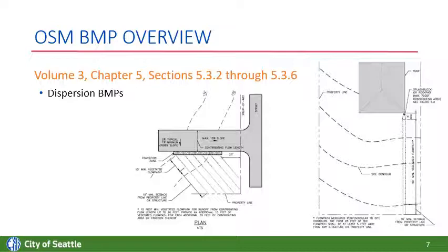That's a category 1 BMP, and it's been clarified for the portions of the site that may be fully dispersed. Some of the modeling assumptions for hard surface areas dispersed have been updated, and that's table 5.11. So again, these figures have been updated to clarify and update the required flow paths for the various dispersion BMPs.